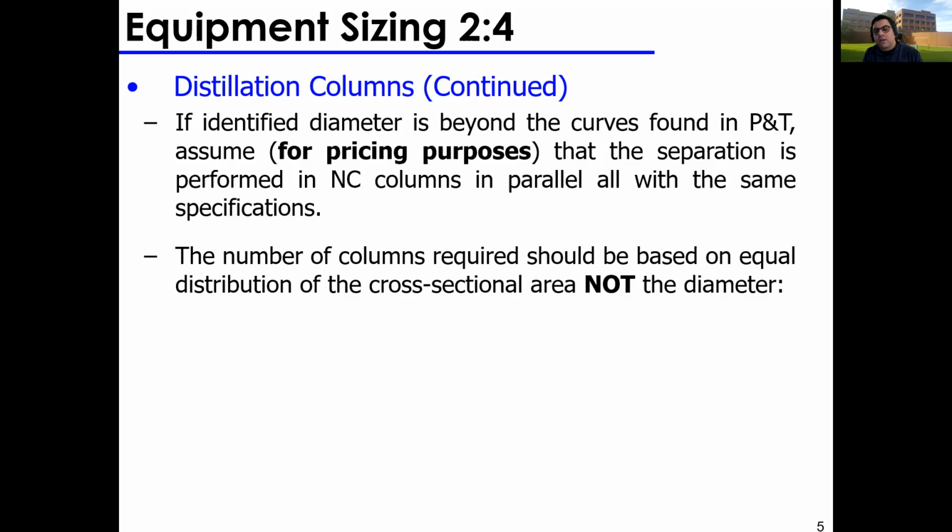So whichever book you're using for mass transfer, Seader, or maybe you're using the book by Wankat, whatever it is, just look at the back for column diameter, find the page with the equation, and plug in the numbers. It's a function of flow rate, a function of density, a function of this and that, and you have your diameter. And you can use this diameter and the height to determine the volume of the distillation column.